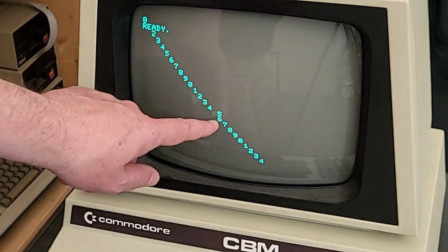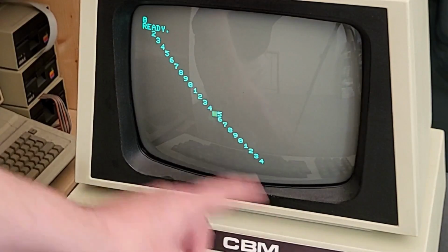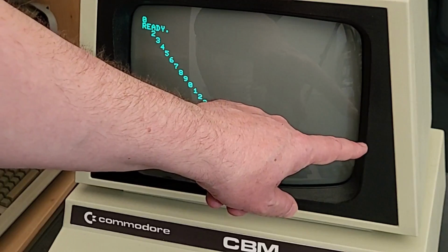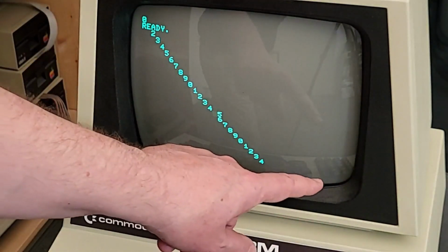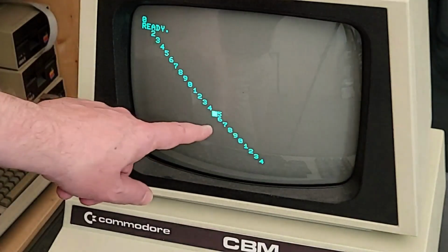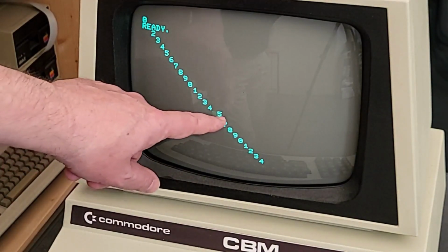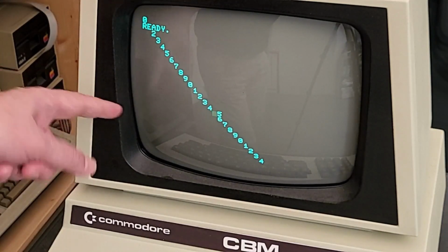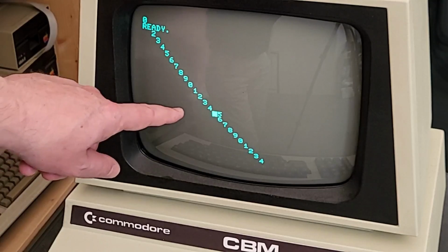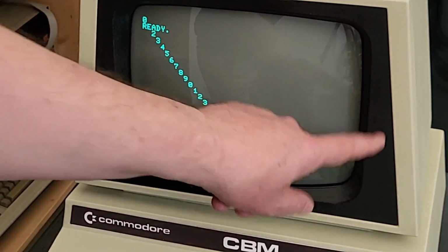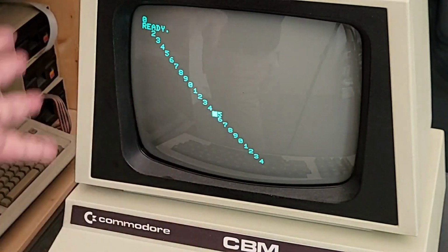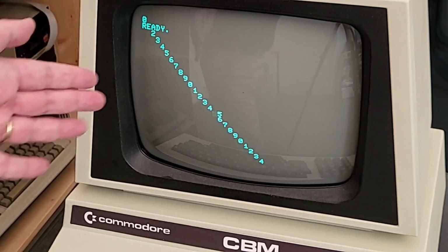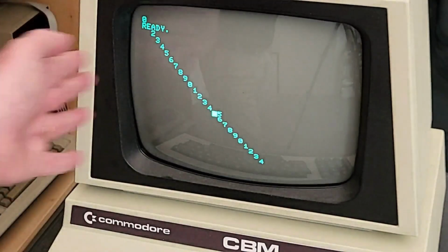And the same happens when I leave that one. Before I leave, the raster line is made 1 cycle longer. Sorry, 1 cycle shorter again. Thus, the next raster line starts one cycle early. And then when that raster line has started, I change the horizontal sync position again so that it's in line here, and then the CRT actually does not know anything. So this is a way you can do a scroll of certain parts of the memory.